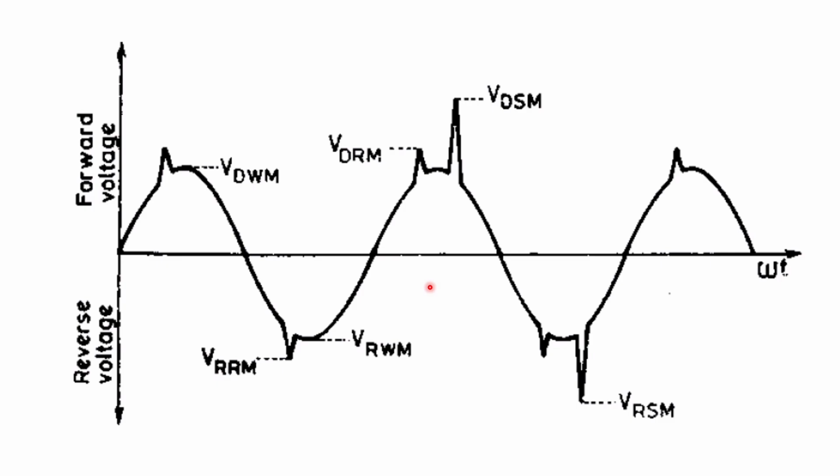So the formula for VT will be VT naught, the minimum forward voltage of the thyristor, plus ID, the current flowing through the thyristor, multiplied with RT, the thyristor resistance or on state resistance. Okay, and this gives your actual voltage drop of the thyristor during a particular amount of current passing through it. Okay, and we take that as an average current value.